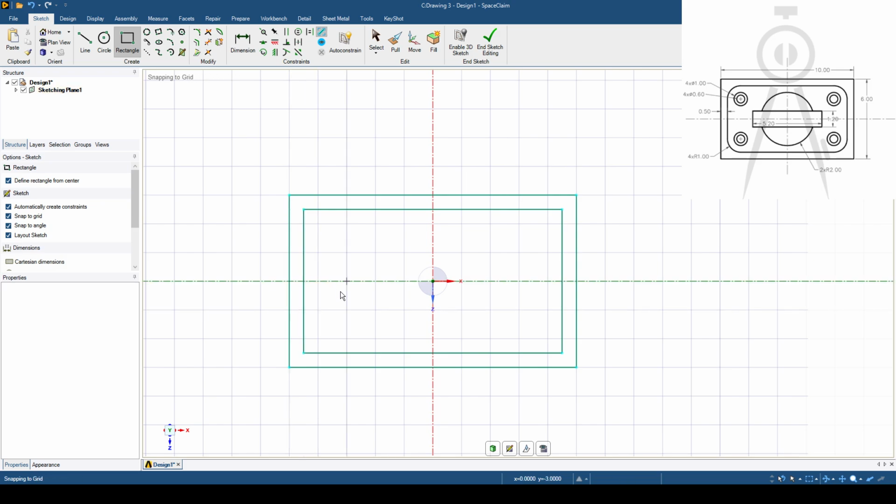In order to save doing trim and so on, we can create them automatically, and the extra edges will be removed automatically by using the feature that we used in the last video. So let's go to the modify tab and choose the create rounded corner.